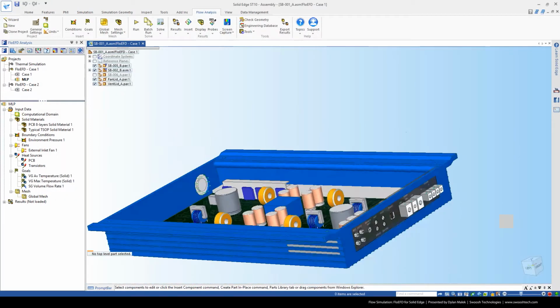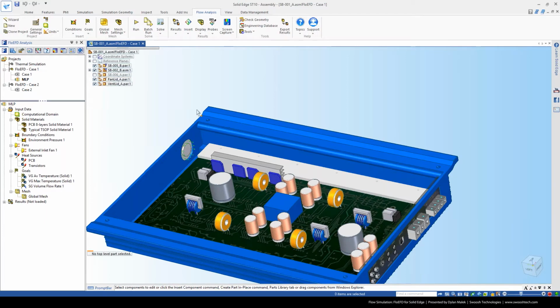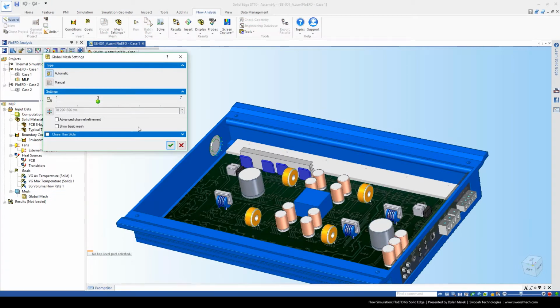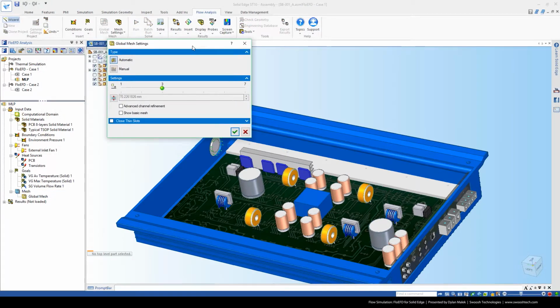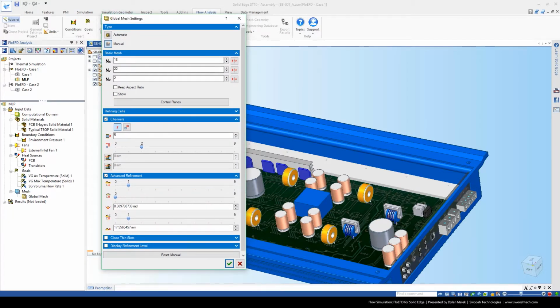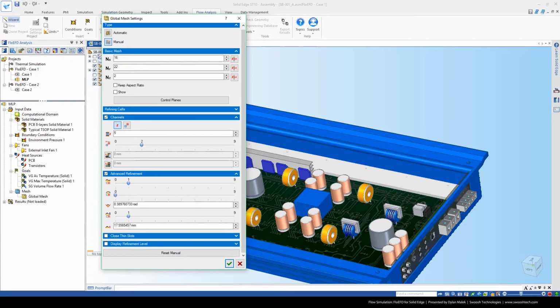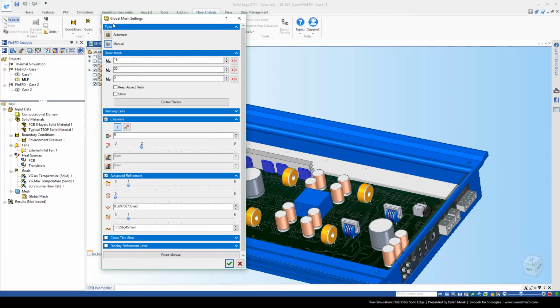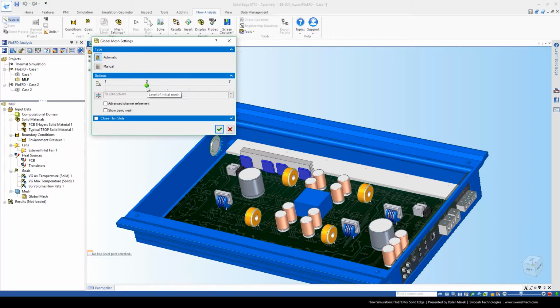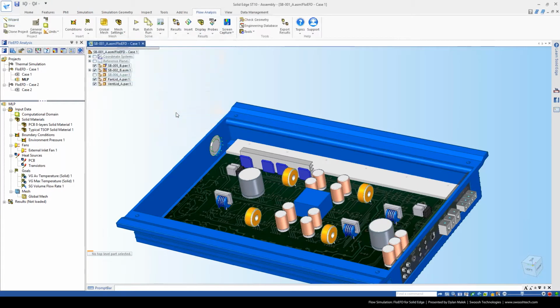Last thing, typically like we do anytime in Solid Edge, like a simulation, last thing you do is mesh the object. So I'm just going to do a global mesh, have this little menu bar that pops up. You go to the manual, just like our other simulation, you have a lot of settings you can define. I'm not an expert in this, so I kind of take the automatic setting, kind of keep it low at first, and hopefully it works. And once it gets refined, I can bump it up to a higher setting. So let's go ahead and accept that.